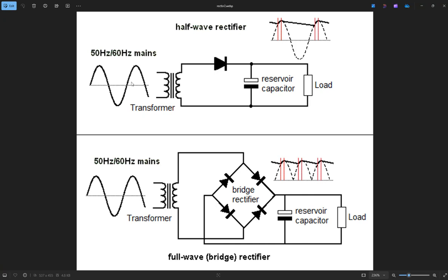So AC signal comes in, transformer, first step. Sometimes you need several different steps of transformers. But anyway, just the transformer stage will convert the AC signal to the voltage range that you need, all right? Second stage is called rectifier. There's one type of rectifier called half-wave rectifier or full-wave rectifier. Or you can say it's a half-bridge rectifier or full-bridge rectifier.